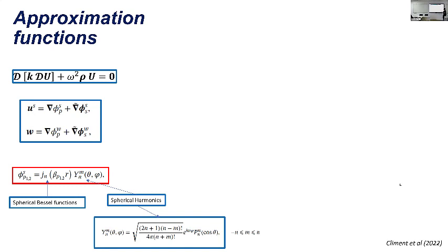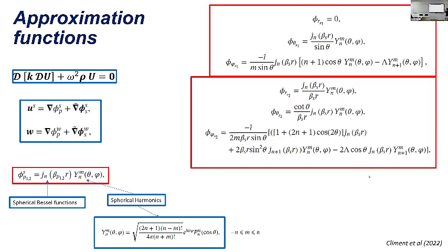After that, we solve the equation for the shear waves. These are the 2 potentials for the shear waves, for each one of the coordinates, because they are vectors here. These are a little bit more complicated, as you see. But with all of that, you can then compute the displacement, substituting in the displacements equation.